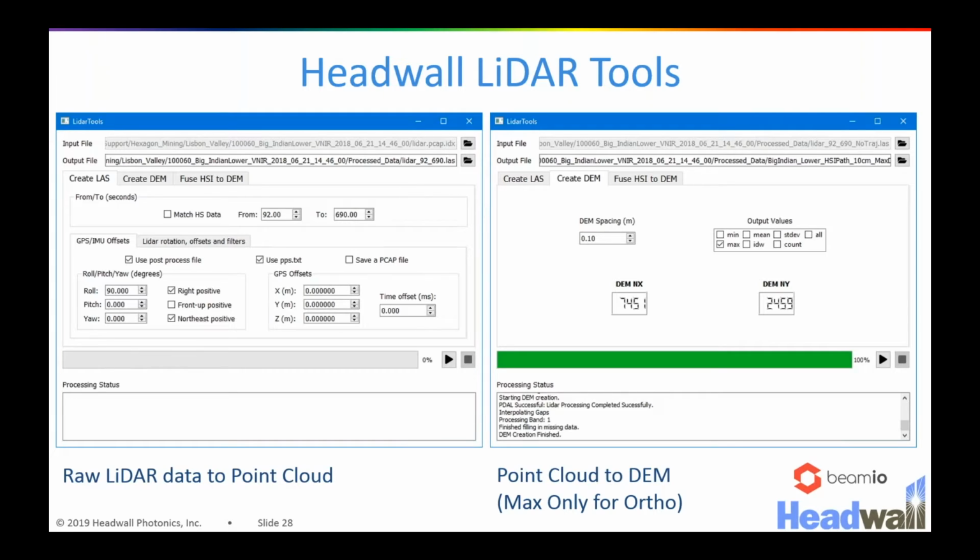And so before you orthorectify, your image will be very wavy. And in order to orthorectify, you need what is called a digital elevation model. So it's basically a map of what the elevation of the terrain is that you're going over. And you can use that to accurately calculate the distance between what you're taking a picture of and your sensor. And so the more accurate that contour map of the ground is, the better your orthorectification can be.